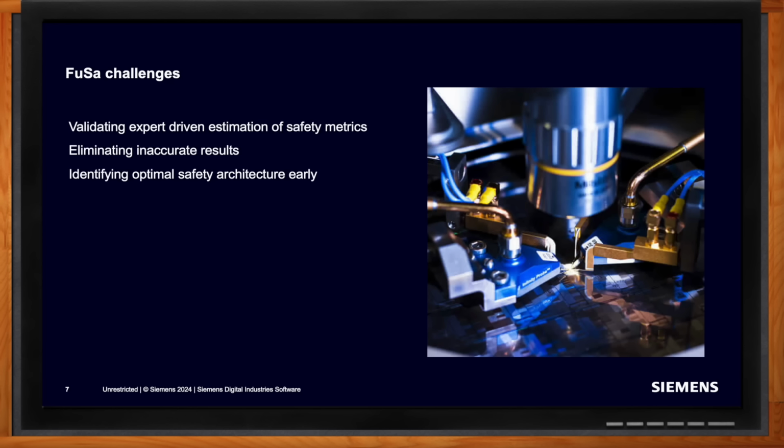Optimizing fault campaigns, there's many ways to optimize a fault campaign, from using the right tools in the methodology to optimizing your fault list, classifying all faults, and then debugging too. Debugging is a really big challenge because many vendors don't have specific tools to debug faults like undetected, unobserved faults, whether they're safe or not. So those are really some of the biggest challenges that we're seeing with customers today.